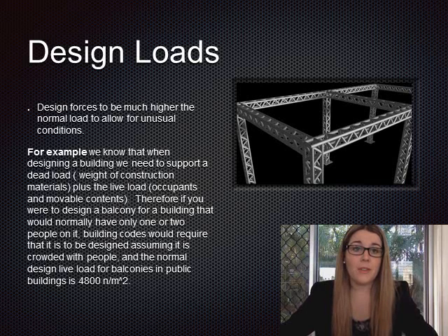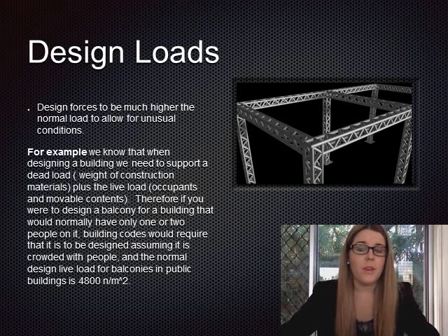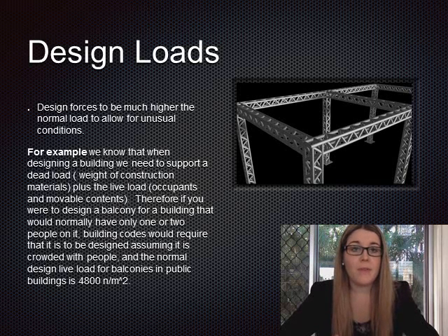Therefore, an added factor of safety should be considered in our design when calculating the design load of the structural member to determine the upper boundary estimate of forces that may occur. So we consider design forces to be much higher than the normal load. This is to allow for unusual conditions that may occur.